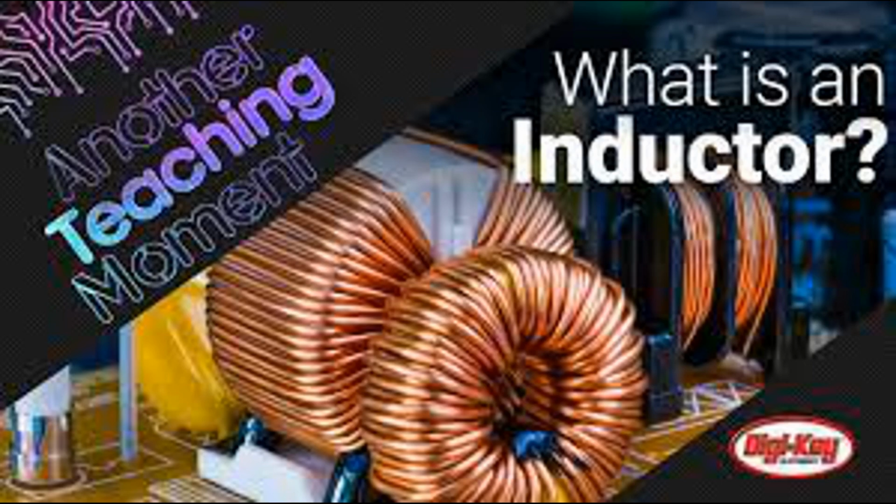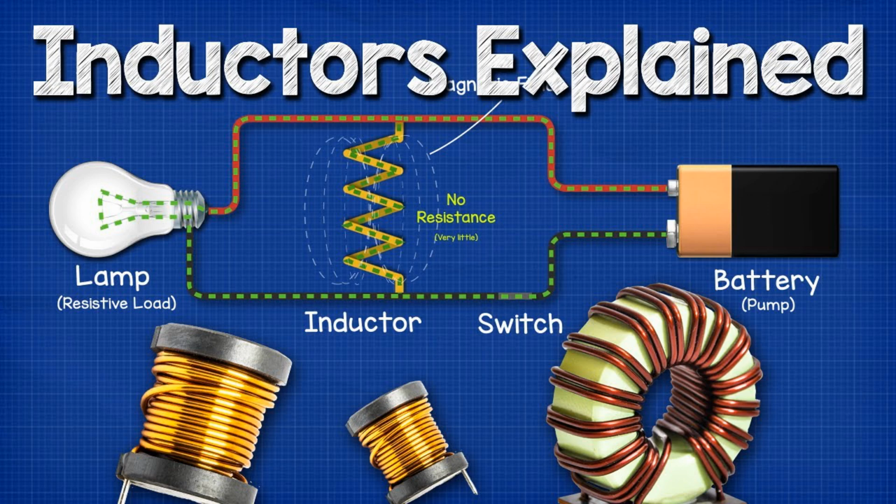Auto transformers and tap-changing transformers are used in power systems to regulate voltage levels, ensuring a stable supply of electricity to consumers. By adjusting the transformer's output, voltage fluctuations can be minimized, improving the reliability of the power supply. Example: tap-changing transformers are used in substations to maintain a consistent voltage level on the power grid, even during periods of fluctuating demand. Audio transformers.